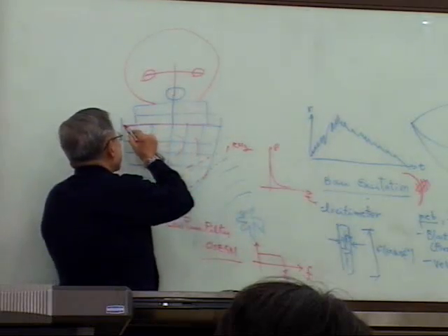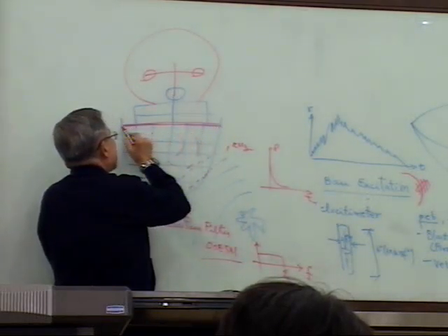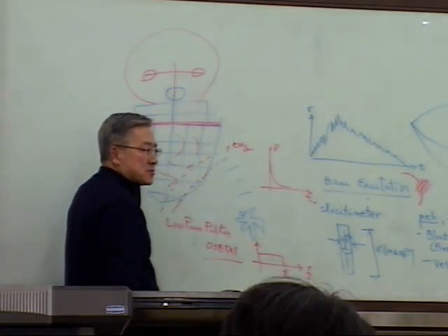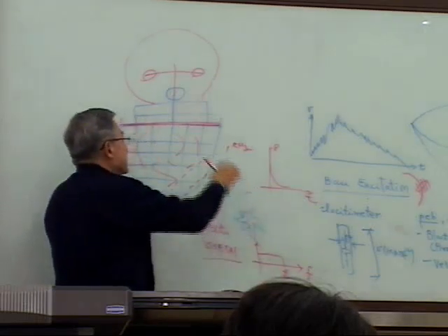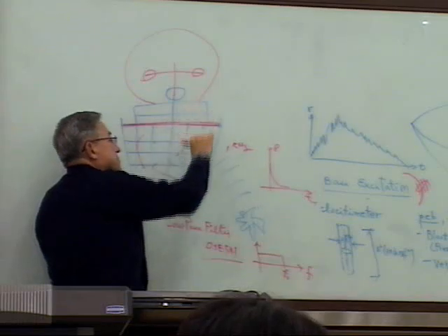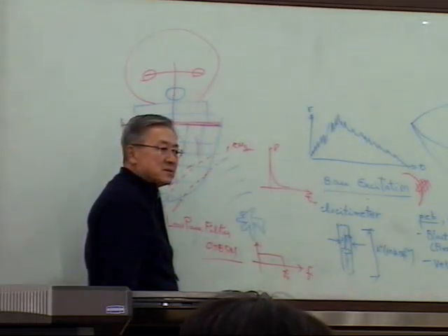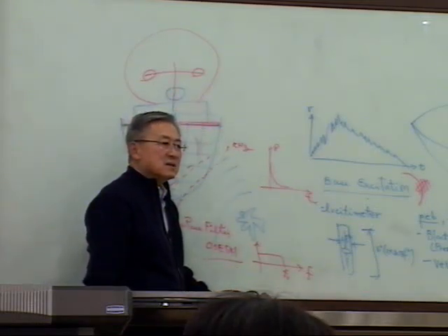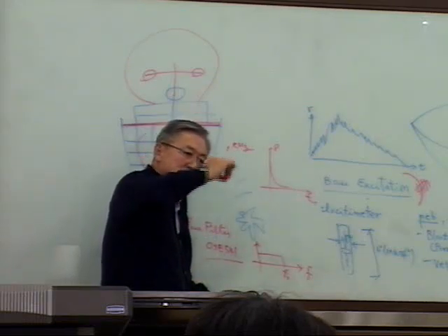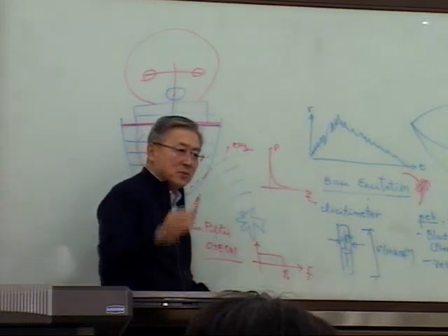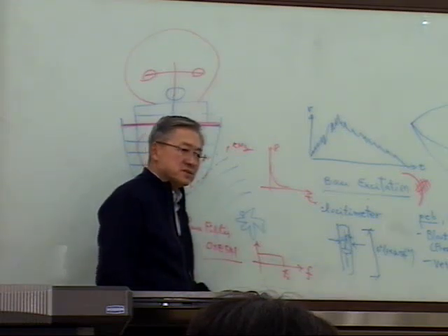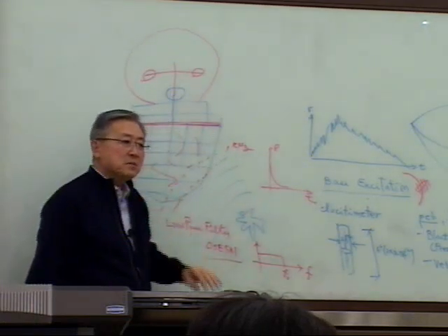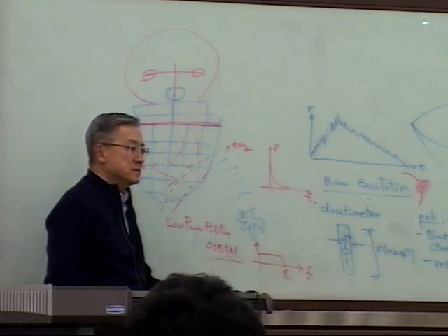And as you look at this main deck, where the superstructure is built on it, this will be in vibration mode. Base excitation to the mast is low frequency vibration excitation, no longer high frequency, because by the time it passes through the ship, the high frequency components are mostly gone.